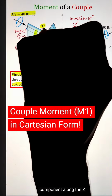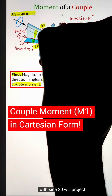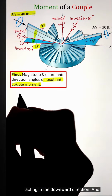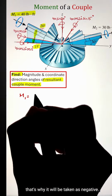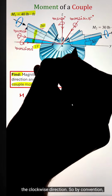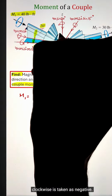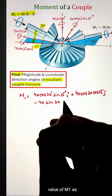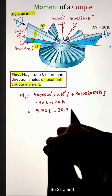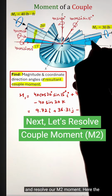Finally, we need to identify the component along the z-axis. So 40 multiplied by sine 20 will project it along the z-axis. However, since this is acting in the downward direction, it will be taken as negative. Also, the rotation is happening in the clockwise direction. By convention, counterclockwise is taken as positive and clockwise as negative. Simplifying, we get the value of M1 as 9.72i plus 36.31j and negative 13.68k.